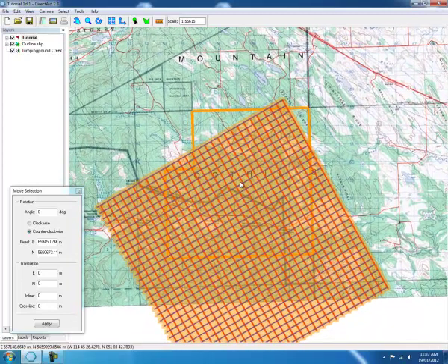The next step is to position the project so it covers our area of interest. In order to avoid renumbering stations later on, we'll want to place the north and east edges close to the edge of the area of interest. Zoom out so you can see the whole project, then click and drag to move it in the map view.